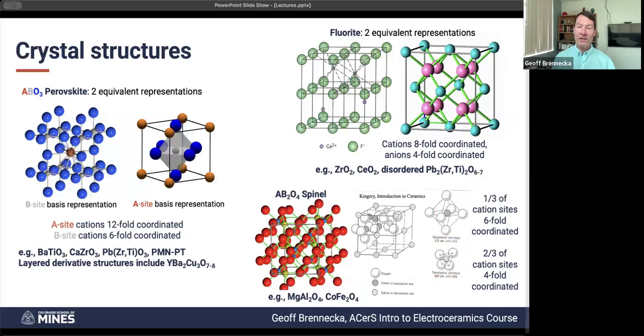And why that matters is because the octahedron has a little bit more space, and is centrosymmetric, or it can be symmetric. By tuning the different cations that you throw into there, you can force one or the other to go into a tetrahedral site or into an octahedral site. And by doing that, you can end up tuning the way in which electrons end up being paired or unpaired. So that's why this structure ends up being very, very important for ceramic magnets.